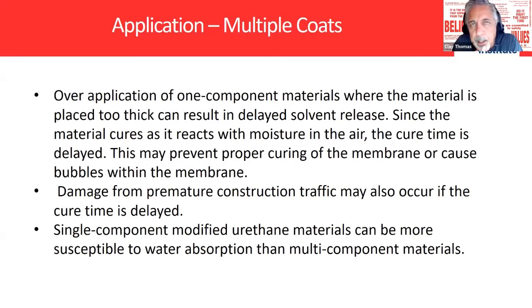And Glenn, in some of what I've read and what I've learned recently in doing this, one of the things is that it's existing construction that has such a high concrete moisture content, which looks crazy, Frank, because a lot of times we deal with this in new construction, where as the concrete reaches its 28-day strength, the moisture content reduces. And Glenn, correct me if I'm wrong, the moisture content allowable to coat, I believe, is 5%.